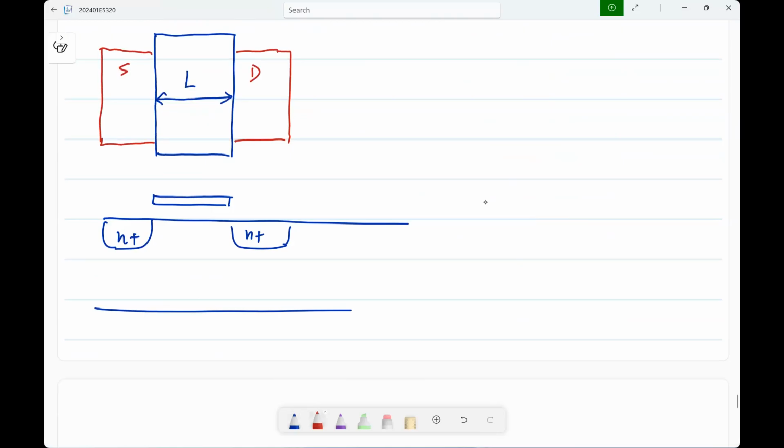And what is the width? The width is the width across which the current flows. Okay. So that is the width. And of course, you will have the gate extending outside because you have to make contact to the gate and so on. Okay. So everything you do is in these two dimensions. Like I said, you have all these layers starting from this diffusion to the gate to various metal layers, and then you make two-dimensional drawings. And that dimension you have control over within some constraints. Because of manufacturability, there will be some minimum and maximum limits for width and spacing and so on. But otherwise, basically, you make 2D drawings of every layer, and you can connect layers to one another through what are known as vias. So that's what you will be doing.